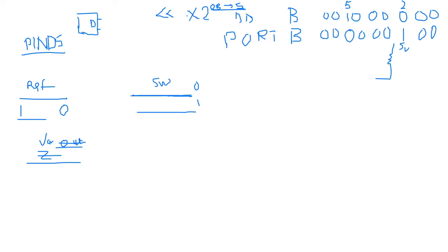So you just simply use the bit that you are interested in. Here we are interested in bit 2 and bit 5. First of all, we want to read the switch, which is our bit 2. When we want to write to the LED, it is bit 5. So we know that we are interested in bit 2. But bit 2 has also been called button pin in the code I've given you, because earlier on we defined button pin as what? 2. So that's information that we can make use of.